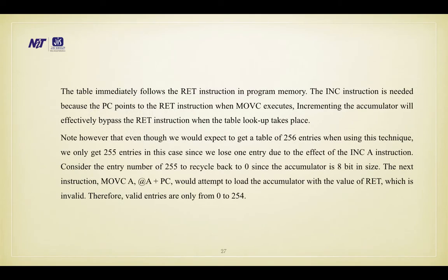The table immediately follows the return instruction in the program memory. The INC instruction is needed because the PC points to the RET instruction when MOVC executes. Incrementing the accumulator will effectively bypass the RET instruction when the table lookup takes place.